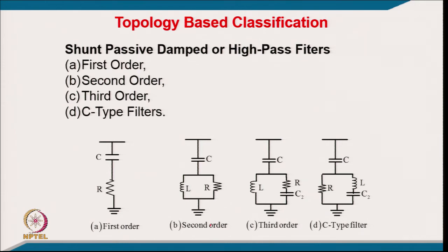So, you can understand that for all higher order harmonics, it behaves with very low impedance, and for the frequency it is tuned to, only the resistance matters, since the capacitor has very small impedance. Only the resistance decides the total impedance. That is the reason the quality factor of this is normally kept between 0.5 to 5. In a tuned filter the quality factor is of the order of 15, or 10 to 30, okay. But here the quality factor goes 0.5 to 5, in that range.